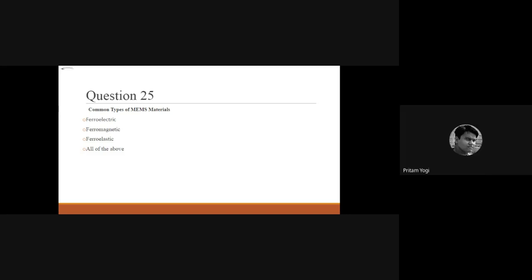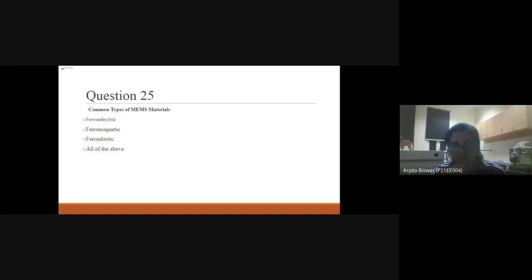Yes, we have to remove that silicon oxide and some portion of the silicon from the back side after patterning it using litho. By using the photolithography process, in some portions of the back side we have to remove the silicon dioxide, and the remaining portion is used as a mask. Where the silicon dioxide is present, the silicon also remains, and in the other portion where we removed the silicon dioxide, this type of shape is present.